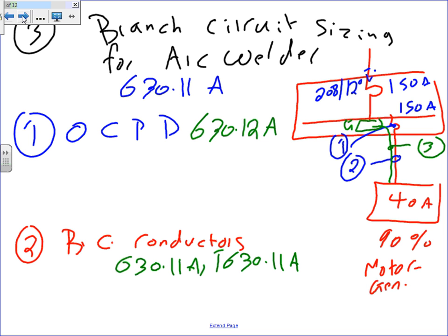I want to remind you, this is the panel that we have just sized, and I picked only one load because they're all the same, one load, and I brought a circuit breaker with a feeder to tie to this load, right? Typical circuit breaker to a feeder. And my job and yours as electricians and engineers and designers is to find the conduit and the conductor that feed this welder. Find the conduit and the conductor, size them, so you can give it to yourself or somebody else to go install it.